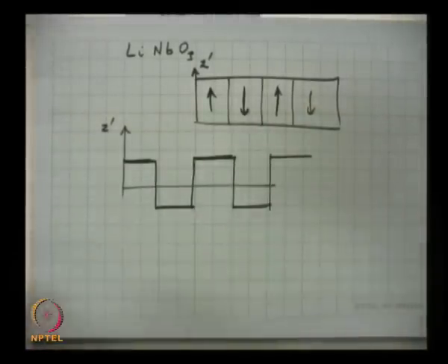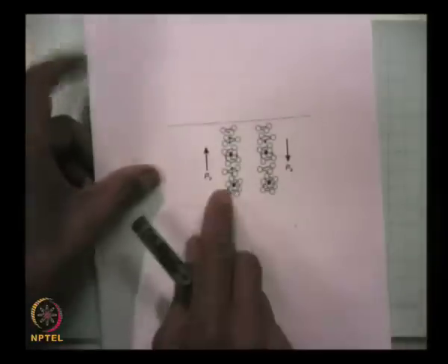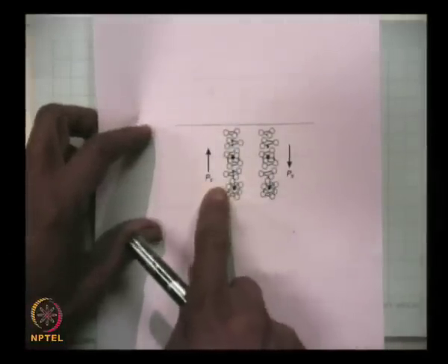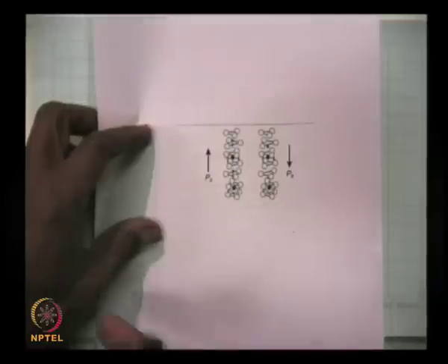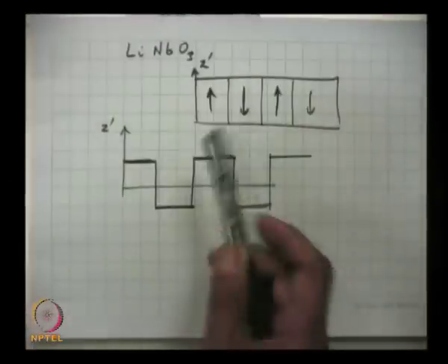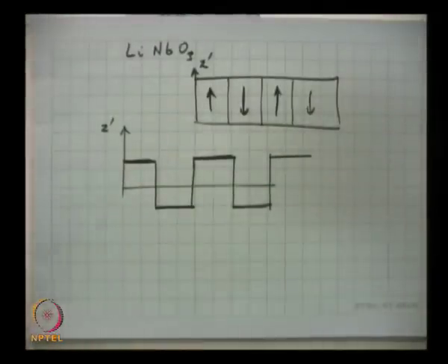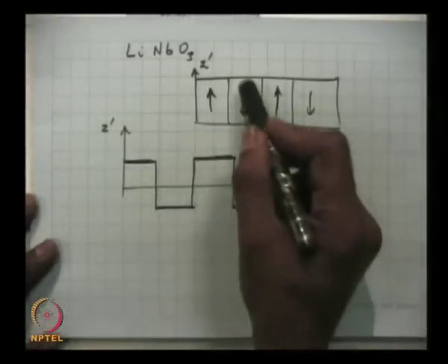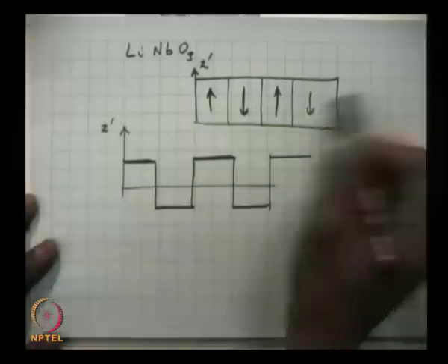So in my laboratory coordinate system, this portion of the crystal will have a positive polarization, a positive D tensor component here, and there it will be negative. So essentially I have to understand what happens to the D tensor if I rotate my coordinate system. What is actually happening is that the spontaneous polarization of the crystal is pointing up here, then down. Instead of taking crystals and stacking them together, I can generate a crystal made up of ferroelectric domains pointing up, down, up, down, periodically.